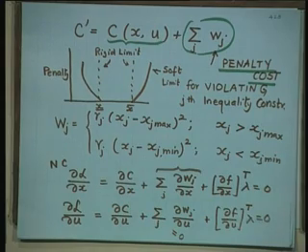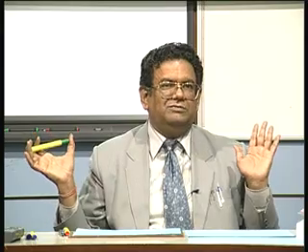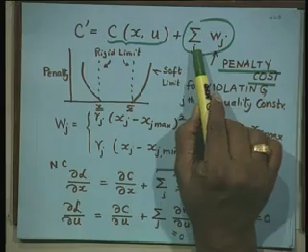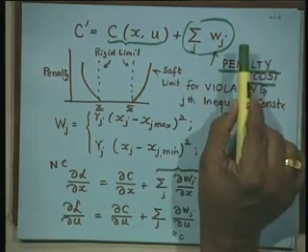Suppose you put your limit so stringent, 0.99 per unit to 1.01 per unit, all the PQ bus voltages will cross the limit, because you have foolishly kept such a limit which is not possible in India, because voltages go minus infinity to plus infinity. So, you have to at least put 0.9 per unit to 1.1 per unit, then it is likely that some of the voltage variables will not cross the limit. So, j, that is why I put it here j, otherwise I would have put all j.